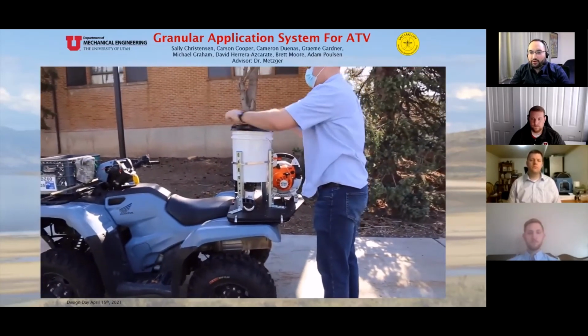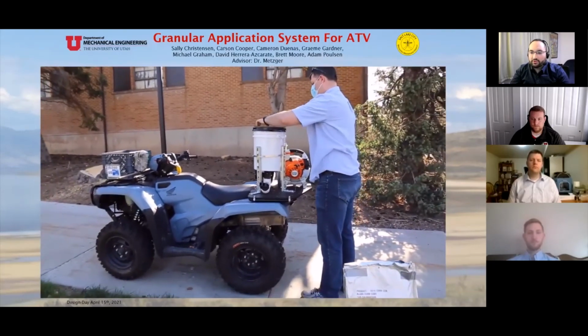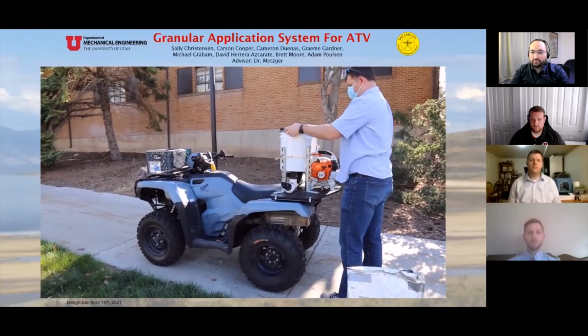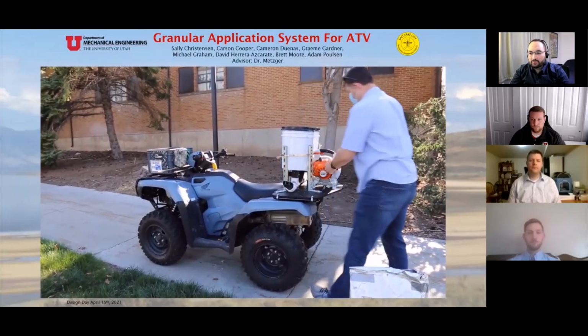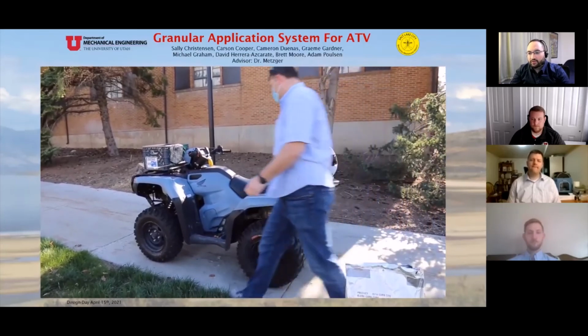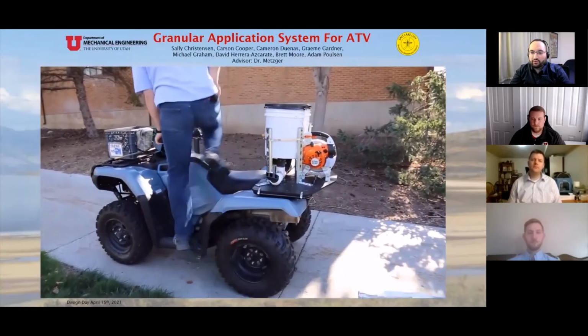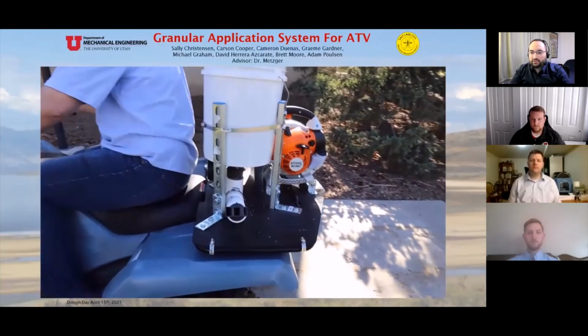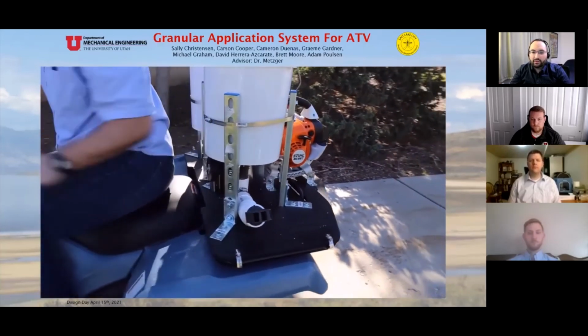After this, the operator will close the hopper with a screw-on lid, which has the built-in gasket to avoid water ingress. The operator will then start the blower system first, and then open and adjust the flow rate gate by using the adjustable handle, which is easily accessible.